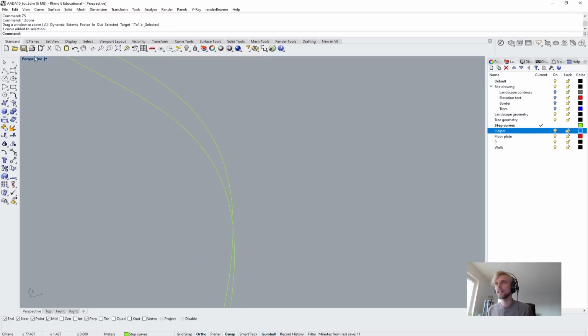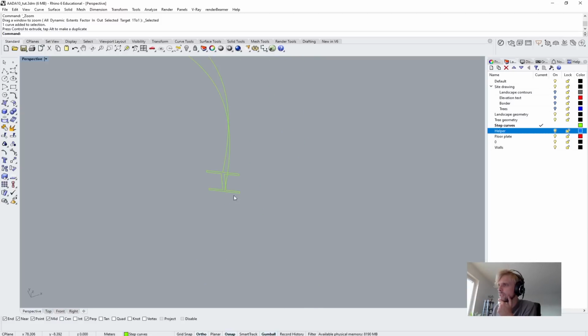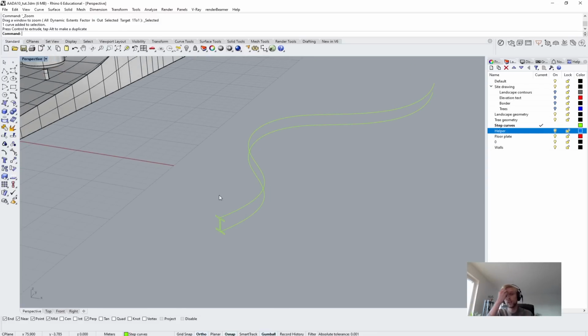There's one more thing that I need to align, and it's the rotation of the I-beam. You can see that the curves are going on at an angle. I want that angle to be 90 degrees according to this section. So the I here is the section of the geometry that's going to be produced. So I need that as close to 90 degrees as possible. This is actually pretty close. Now this is all that we need for sweep between two rails to work.